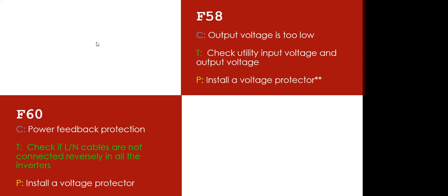So if you want to do that, you connect the inverters together, then you connect all your battery bank together, so that all the inverters will have the same voltage from the battery. The same thing we do for solar, only if it is a high voltage inverter.